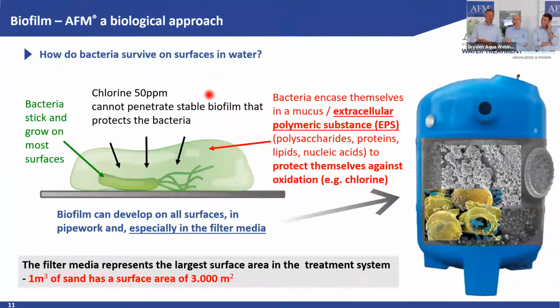It has to oxidize from outside to inside, and by this it is losing concentration. So even if you go with high chlorination, you will remove maybe 99.99999 whatever percent. But the moment you have 1 or 2 survivors, and the conditions are good, with enough food and good temperature, you're back in problem. And very often in a chlorinated system, especially a permanently chlorinated system, after a period of time you can create a bigger biofilm problem than before.